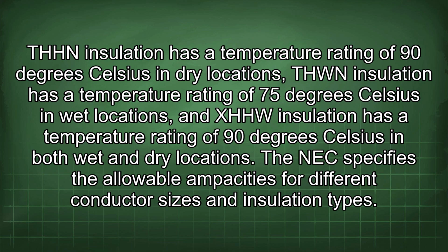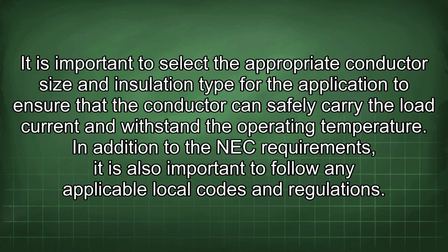The NEC specifies the allowable ampacities for different conductor sizes and insulation types. It is important to select the appropriate conductor size and insulation type for the application to ensure that the conductor can safely carry the load current and withstand the operating temperature. In addition to the NEC requirements, it is also important to follow any applicable local codes and regulations.